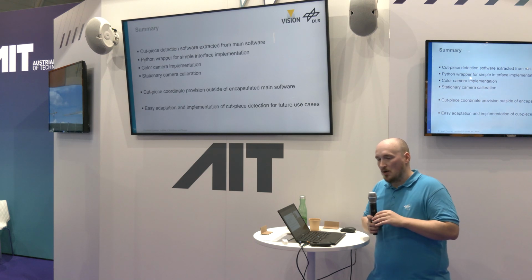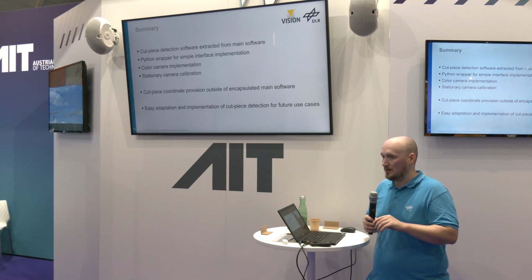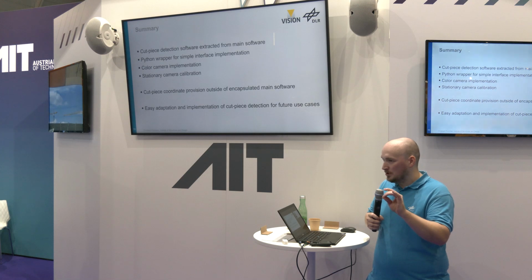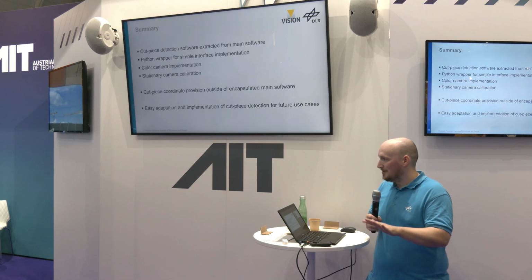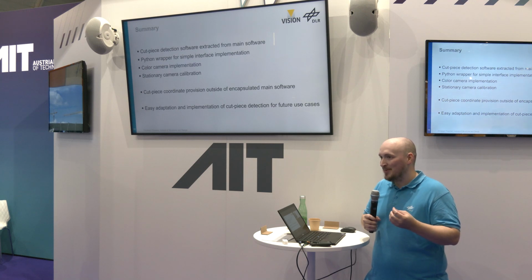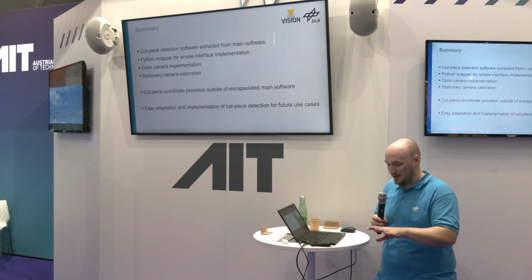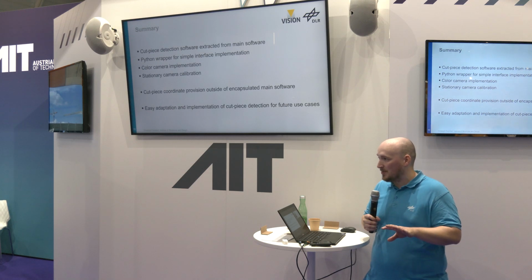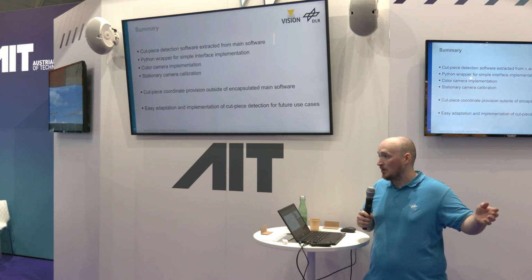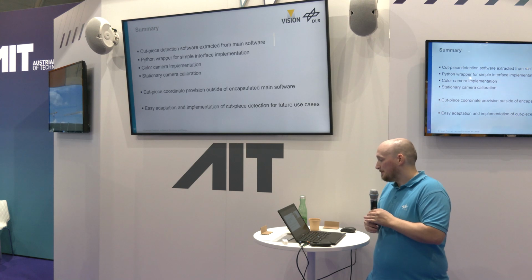And also this approach of helping the worker in his task is much more sufficient than automating this process completely, since humans have rather nice tools in terms of hands. They can do things very precisely, and they have a really nice and fast feedback, which robots usually don't have. So you can take advantage of the worker's skills he learned over years in the draping, and simply let the robot do the stupid tasks by delivering 4-meter long cut pieces, which would be really difficult for one human alone, and stuff like that.